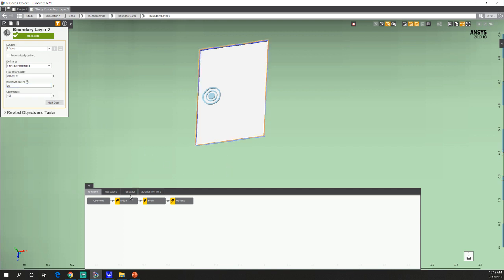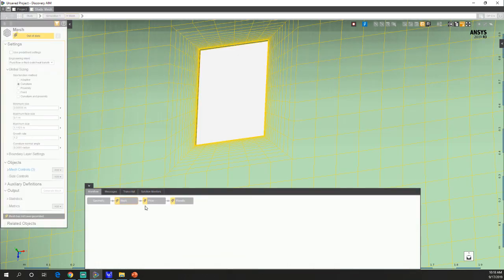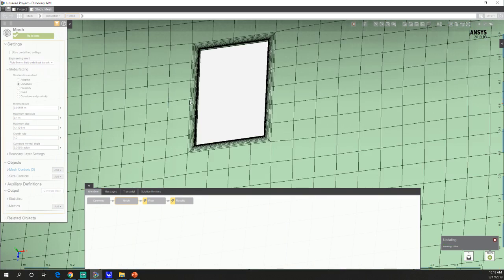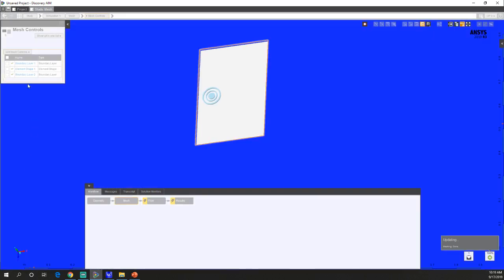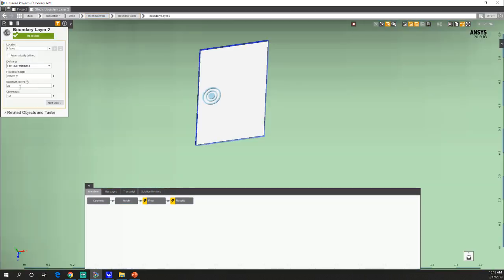The other thing is that when we generate this mesh, we want the transition to be smooth. So we don't want there to be a huge difference between the element before and after, like a big element right next to a very small element. So we want to transition that, craft this mesh much more carefully.